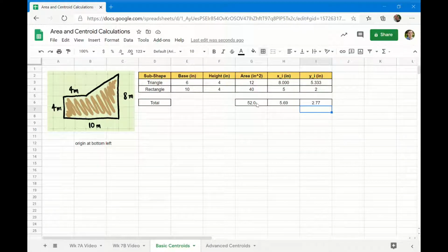I'm going to switch over to the whiteboard now, and we're going to talk about the next topic, which is moments. We will return to centroids and areas throughout the year a little bit. I am compacting this whole thing down into more or less one semester, but the centroid of the tables and desks and things that we're making is really important, because we know that the center of mass is going to be somewhere near the middle of that, somewhere around where that centroid is, and that is going to be very critical for knowing whether this thing is going to tip over. Is it safe? Especially if you have things that fold out. If you have a computer that extends out, you've got to keep track of that so that it is just not going to tip. That's one very practical use of the centroid.